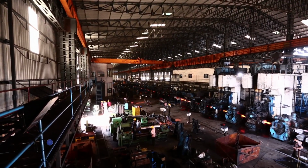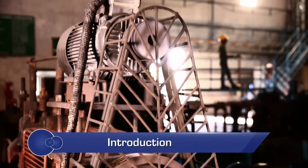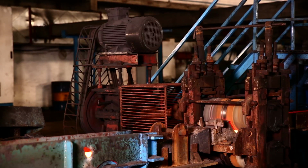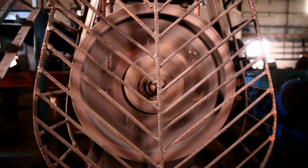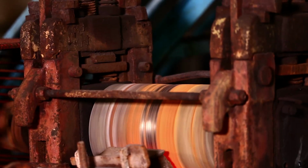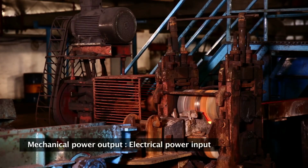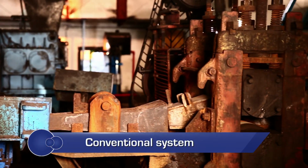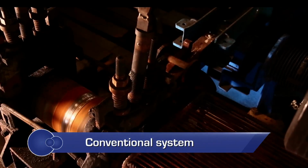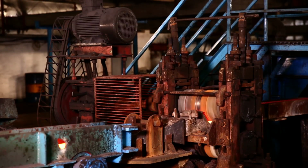Three-phase induction motors are most commonly used to run various applications in a re-rolling unit. These range from the mill stand motors of higher ratings to lower rating motors used in conveyors. Motor efficiency is defined as the ratio of mechanical power output to electrical power input. In most of the applications in a rolling mill, conventional motors are used with an efficiency range from 75 to 88% depending on the size.